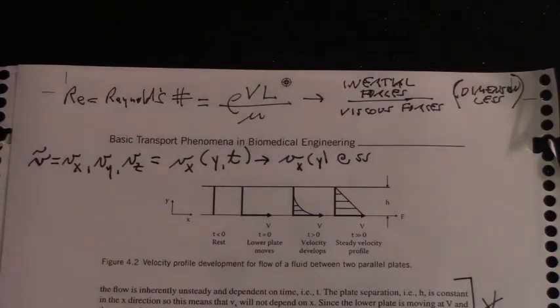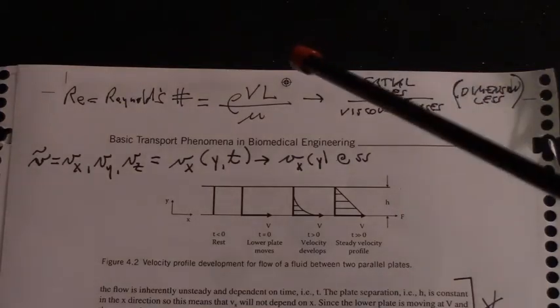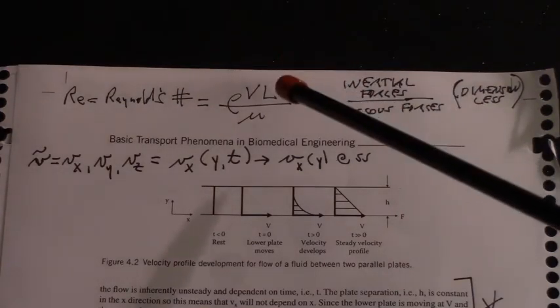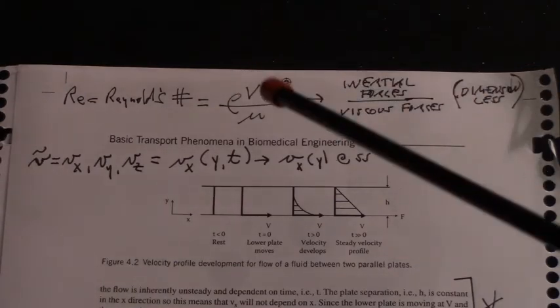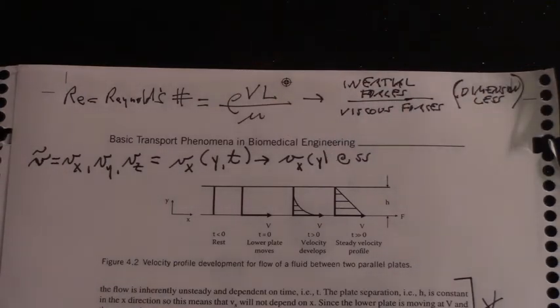We would expect that flow to be very viscous because the characteristic length would be the diameter, which is very small, the velocity is very low, and the viscosity relative to those terms is high. That gives us a low Reynolds number, and we have what we call laminar flow. Laminar flow is that nice glassy flow, and I gave you some ideas of what it means in terms of soldiers marching in their ranks and files.